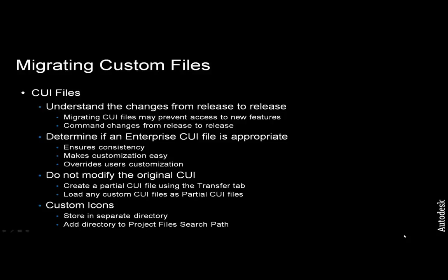It is important to understand the changes from release to release. Migrating a CUI file from a previous version may disable the new features in the recent version. It's important to understand that commands change from release to release. So understand the commands that are in the CUI file that you're looking to migrate and ensure that you're not overriding any new features or changes in commands.